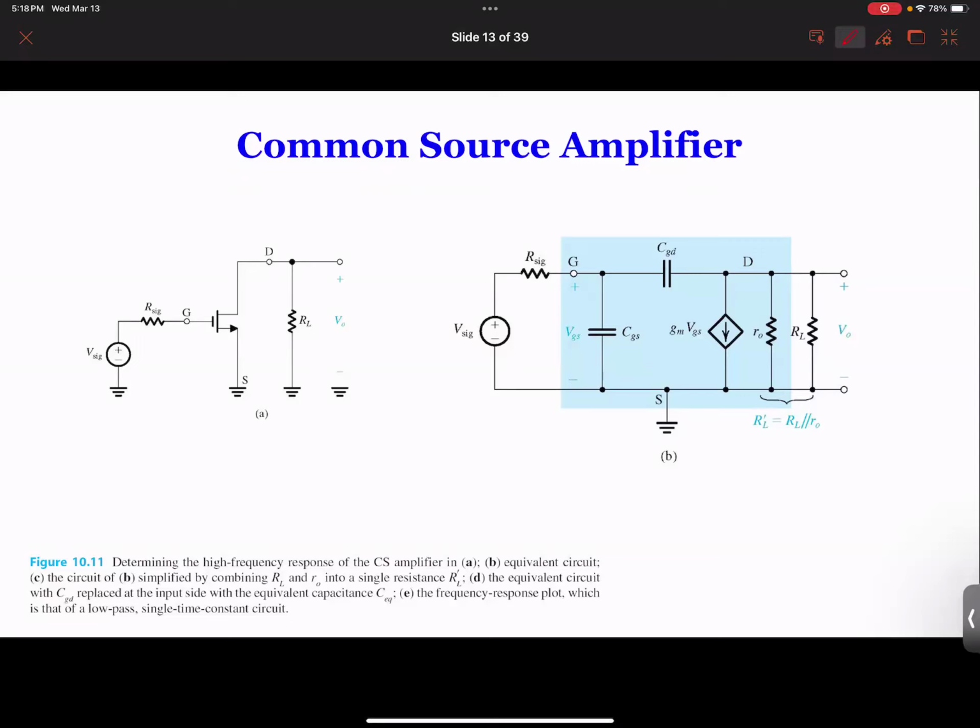Okay, so for this one, we have a small signal circuit over here, but we didn't replace it with the small signal model yet. So now we can actually draw the small signal circuit. And you all know how to draw a small signal circuit now, but remember, at this time we need to include the capacitance. So the initial small signal circuit was this one, plus the open circuit at the input side.